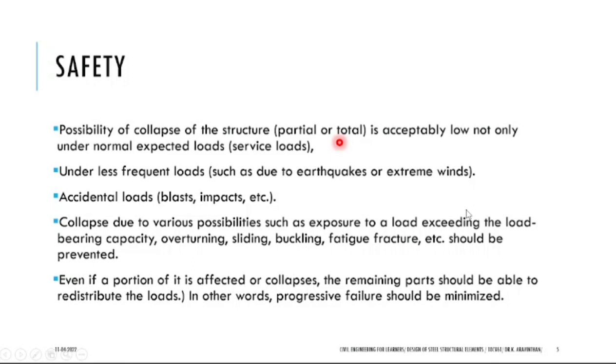See, an eggshell will collapse only after having the cracks. Yes or no? Once you have the crack, you know that it is going to collapse. So the building should be designed so that the structure gets cracked and it collapses only after the second stage. Okay, the first stage is called cracking, then the next stage is the plastic hinge. So the structure's first level is cracking, but after that, imagine that your slab is being cracked now or it is going to fail now.